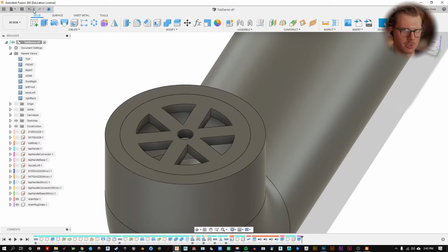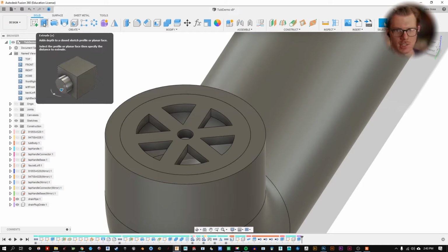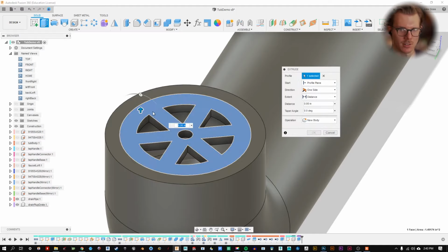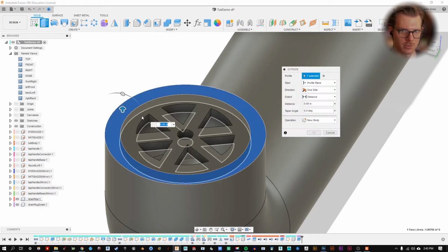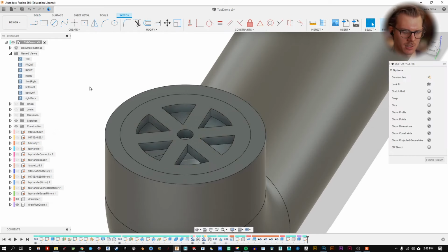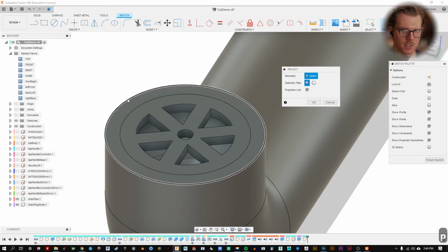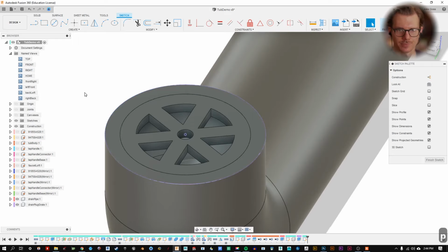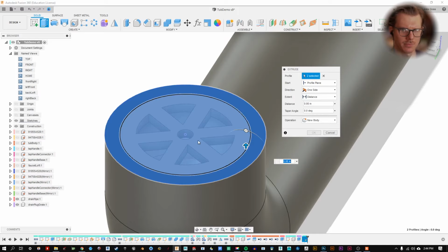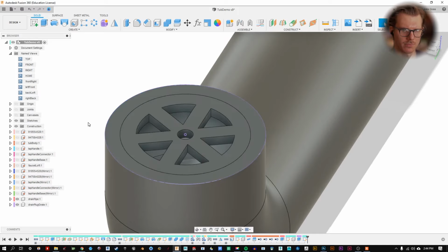I'm going to do another extrude command, and I'm going to leave this pipe visible for the beginning of it. I'm going to try to do this without making any new sketches. Let's cross our fingers. So new extrude. I'm going to click on our grate. And I'm going to click on the pipe, but no dice. So foiled. Because these are separate components, it's not going to let me do it. And that's okay. So let's make a new sketch. Click. And I'm going to say project, P on the keyboard, click on the outside of that pipe. Now if I hit finish sketch, we should be able to do this. Hit extrude, bam, bam. Let's hide that pipe.